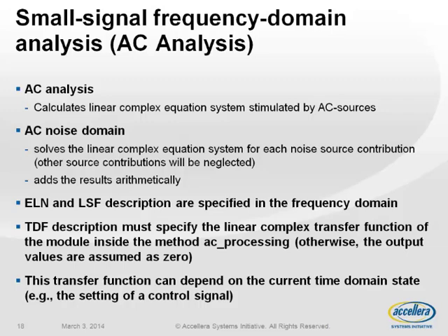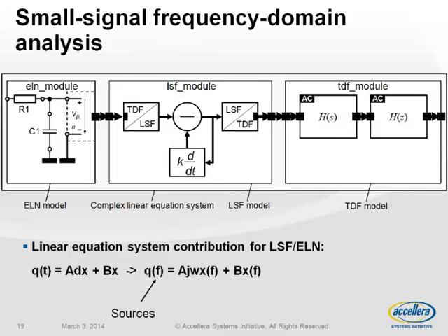There's a particularity that the ELN and LSF models already provide these linear equations contributions, but the TDF modules which you are writing, they don't have yet this AC behavior assigned. So that is something you will have to provide. Otherwise, they will simply contribute no solution, and so the output values of these modules will be assumed 0. Here you can see such a signal processing chain where you have ELN modules at the input, some LSF modules, and then at the end of the chain also some TDF modules.